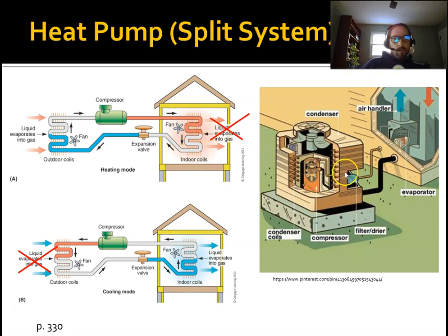And so it looked more like this in the field. You'd have your outdoor unit like this, and there's coils sort of wrapped around here with little fins on these to facilitate the heat exchange. Here's your fan that gets the process happening. There's your compressor, and then your refrigerant lines that go in and out, and then you'd have your coils inside, usually in a basement, but it could be in an attic or wherever.